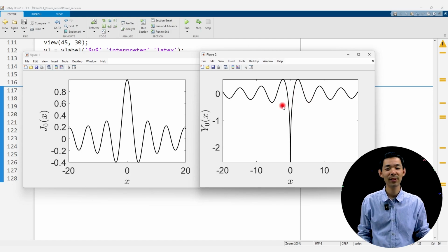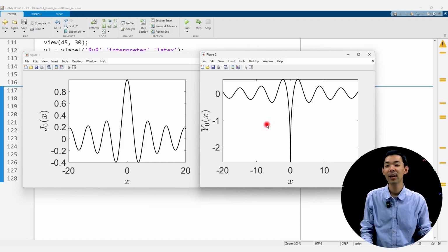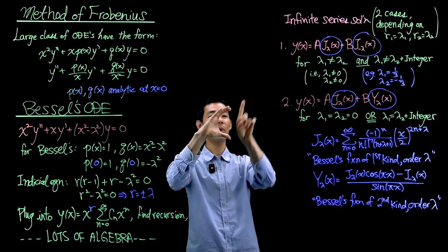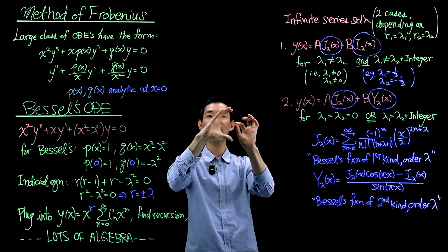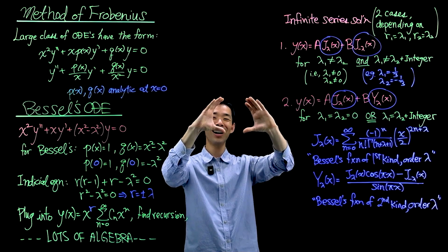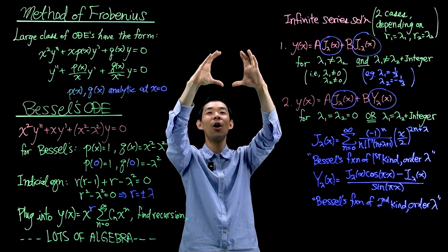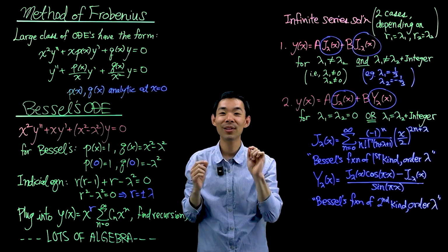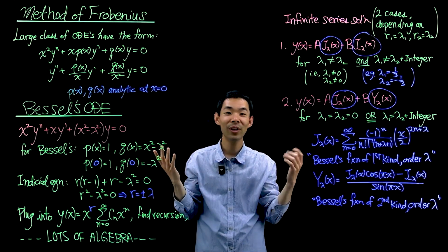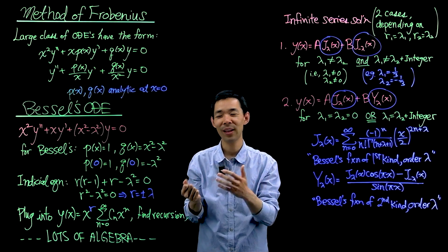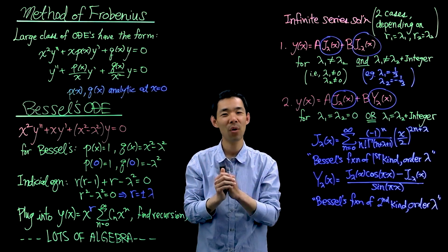And actually, that's a very important point. In many problems that we'll solve in cylindrical polar coordinates, we're going to have a boundary condition at the origin. So imagine you have a cylinder, and there's radial polar coordinates pointing out from the center of the circle. You're going to have a boundary condition at the edge of the cylinder at r equal to r naught, for example. But at the origin, you're going to need another boundary condition, a constraint. For example, the temperature can't diverge off to infinity, or the concentration of reactants can't diverge to infinity. You can't get mass flux into the origin.